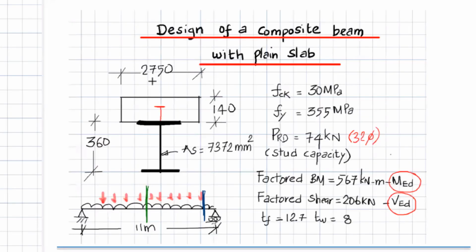In the example I'm going to show you, I have already used the value of the B effective as 2750. So I'm not going to show the calculation, but I only say the B effective has to be calculated depending upon where you are going to do the design. Now coming to the simple problem, so every one of us can relate. What about the shear connection? Full shear connection. I don't have to worry, there's no slip.